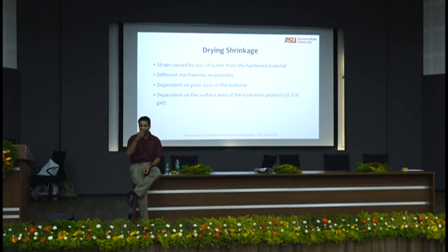Have you seen that corrugated tube method to measure autogenous shrinkage? People have started selling it now. That kind of measures both together. If you want chemical shrinkage, you can actually do it. You can take a very thick balloon, put the cement paste in the balloon, seal it nicely, put it in a water bath, and see the mass loss happening underwater, and compare that with the initial stage. There are some nice, very simple ways of measuring chemical shrinkage out there if you want to do it.